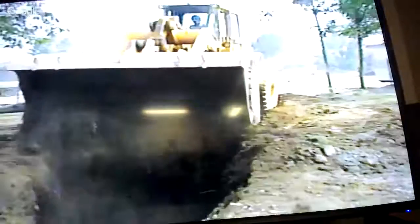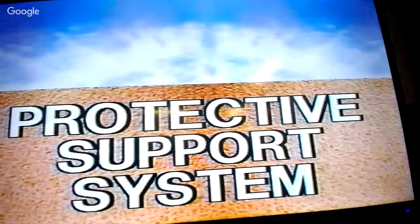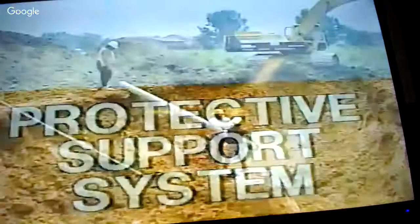It is not uncommon to have an excavation site containing a combination of soil types. Every location differs. That's why soil classification is so important. Once the soil classification has been made, you will know which protective support system should be used in the trench.